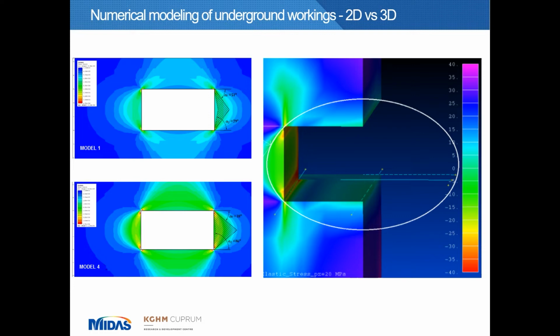If it is not necessary to take into account changes of geometry and variability of parameters in the vicinity of the excavation, it can be stated that results from 2D and 3D analysis converge with each other very well. Here we compare the results of calculations made for a few variants of tunnels excavated in various types of rocks with different cross-section shapes. And indeed, according to the results, if the material is homogeneous and the excavation is performed in one direction without visible changes in the geometry of workings, then two-dimensional models will reflect well enough the actual situation in the surroundings of the analyzed area.